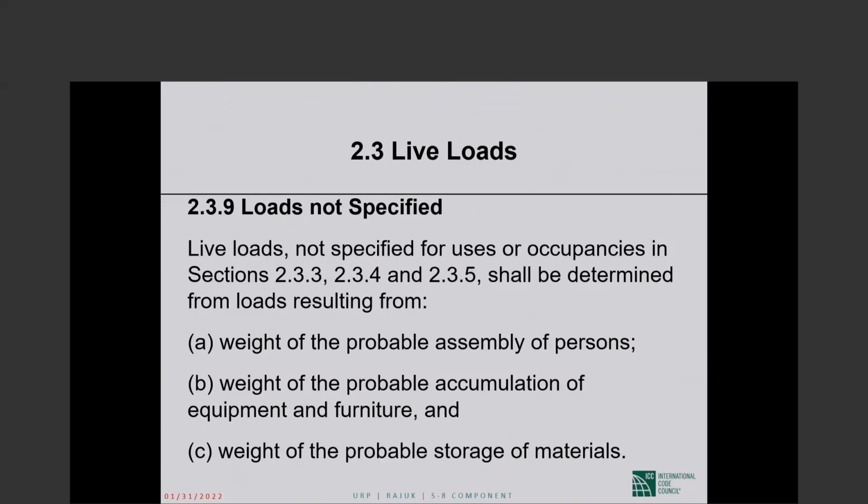So roof live loads comes from, let us say, 6.2.3 is the main table that you will go to, and you will go to 6.2.4 when table 6.2.3 sends you there. That's the best way to say it.